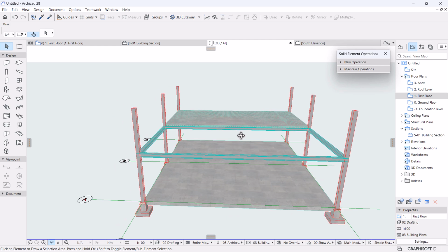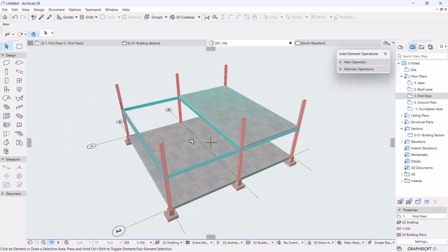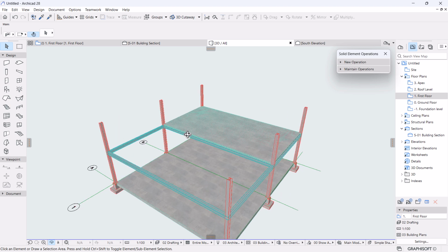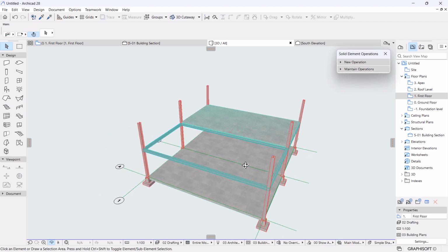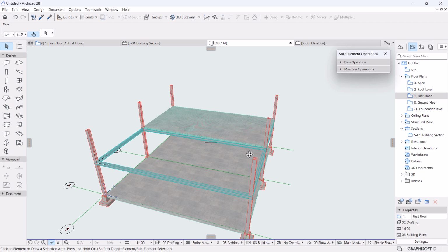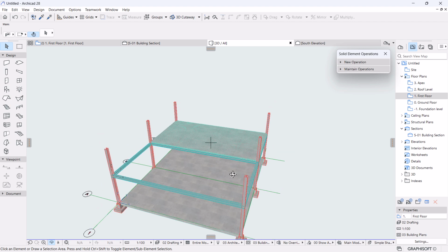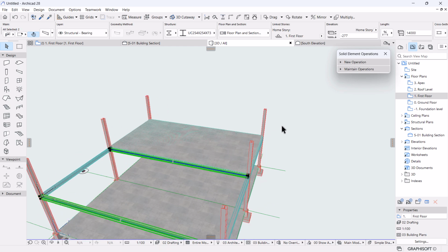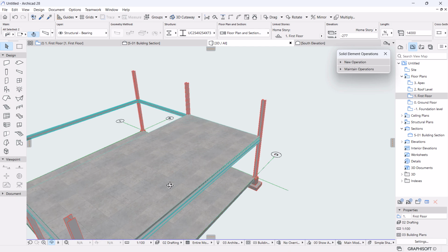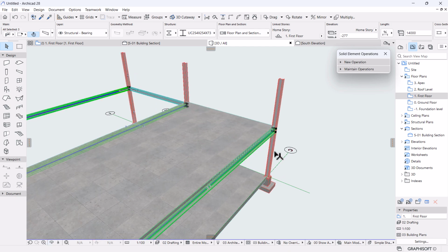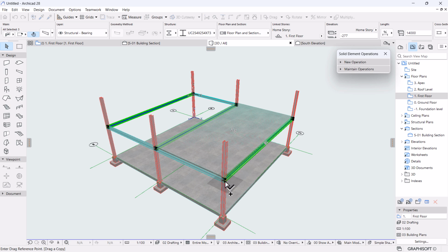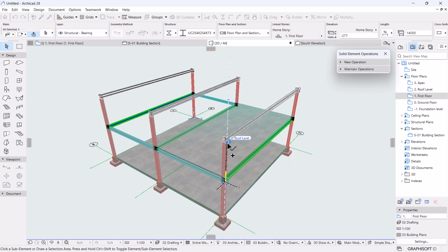All right, let's move on to the roof structure. The roof structure we're going to use more like steel as well. It's going to be more like a portal cabin or a framework, a portal frame structure. So what I will need is to have also the beams as the tool going up. So I'm going to select all these horizontal beams that cuts across like that, and then Control Shift D to make a copy to the top like that.